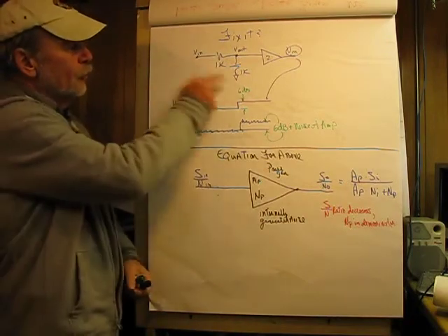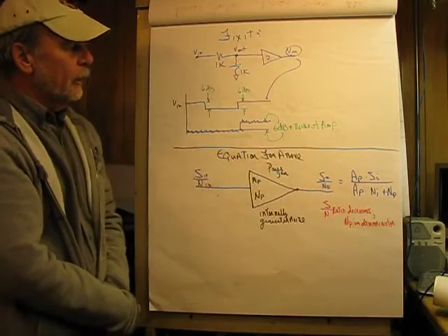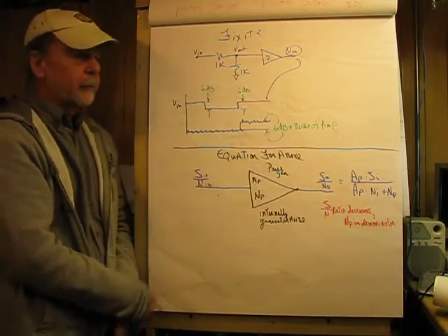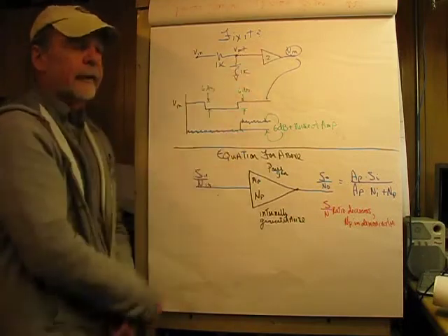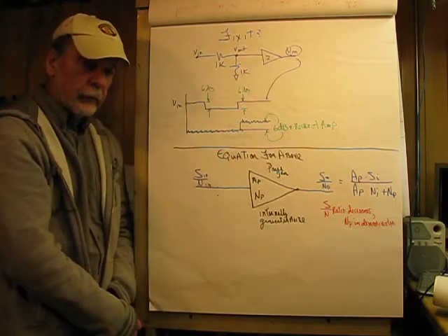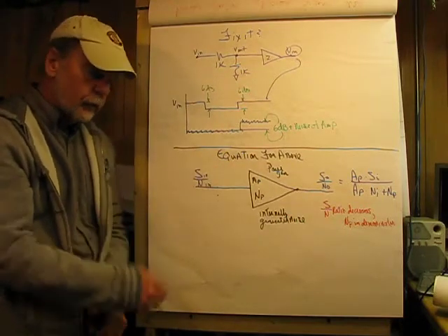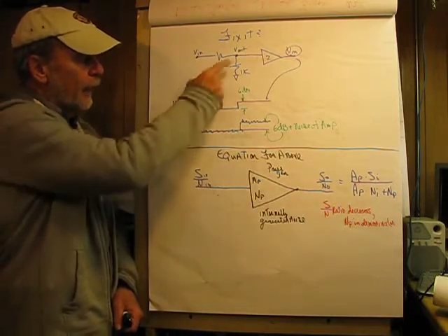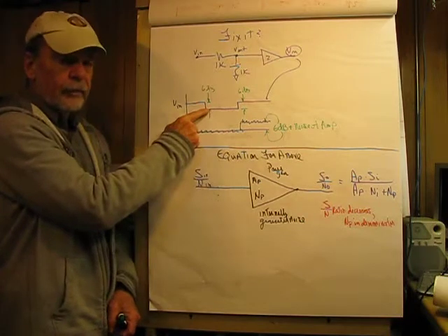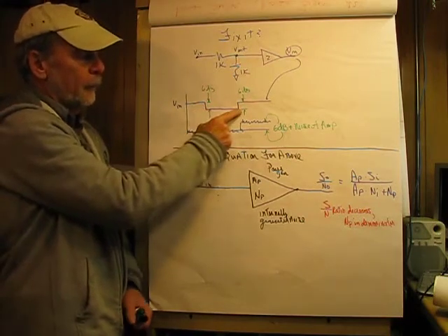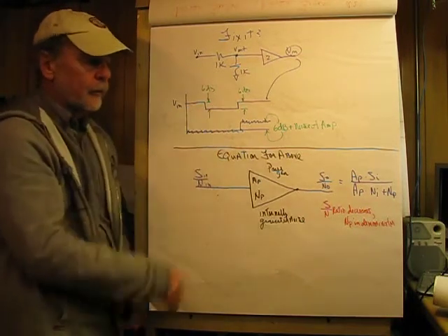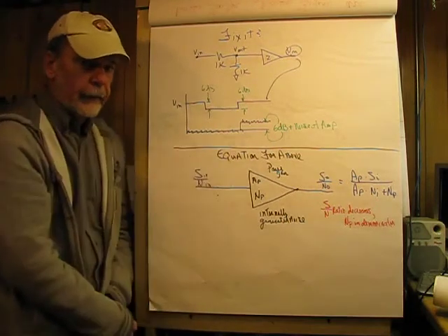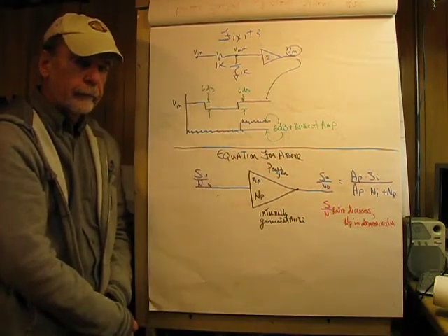So here's the same circuit, but I got a ×2 amplifier on the tail of it here, and my desire here is to get back to our original voltage Vn, and hopefully that will restore the signal to noise ratio. And what I find is when I put the divider in, I dropped 6 dB as before, and then when I put the amplifier in, it increased it 6 dB. But it also increased the noise floor by 6 dB.